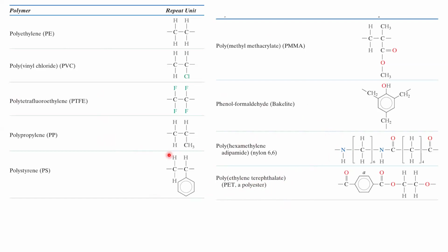Based upon temperature behavior, there are three classifications of polymer: thermosets, elastomers, and thermoplastics. Thermosets are, for example, cross-linked polyethylene, XLPE, used for dielectric and electrical cables. In the same way, there are different types of thermosets. Rubber is an elastomer, and we can see different types of elastomers like chloroprene rubber, natural rubber, silicone rubber, and latex rubber.